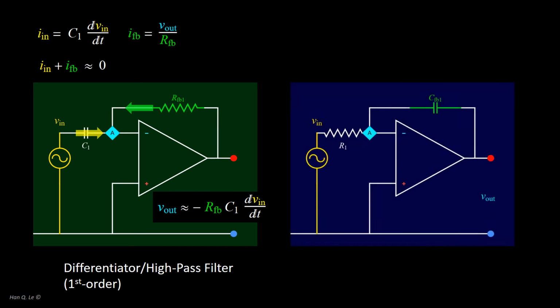Op-amp transimpedance amplifiers can be used to perform capacitive differentiation or integration. The transimpedance amplifier for differentiation on the left side is discussed in Part B. For integration, as shown, input voltage Vin is coupled to the input resistor R1, resulting in input current In at node A of the inverting terminal.